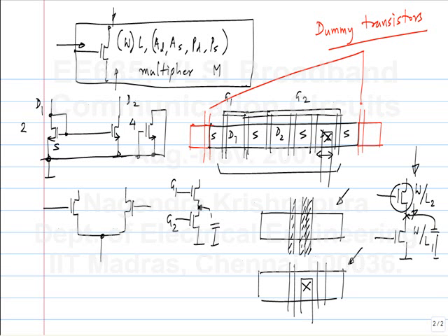So far we discussed the characteristics of low pass channels. We know that it causes ISI, and then we also discussed how to make an equalizer at the transmitter. The transmitter is a special case because the input signal to the filter is discrete. In the simplest case, binary, but it doesn't have to be binary, it will be some small number of discrete levels.